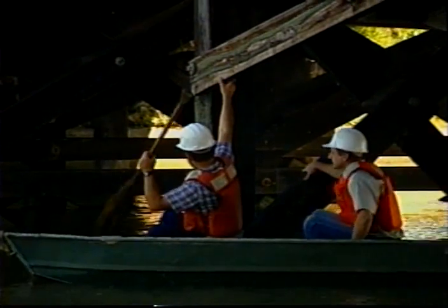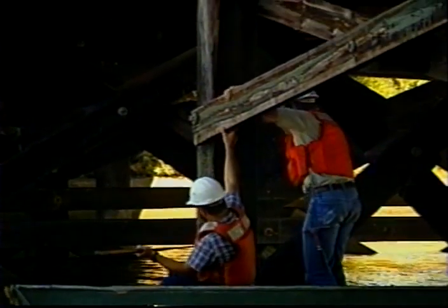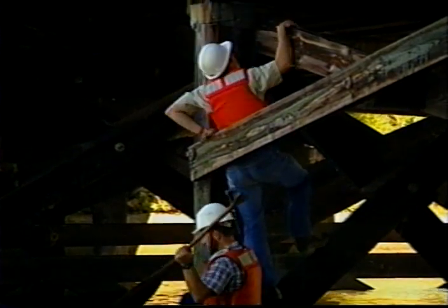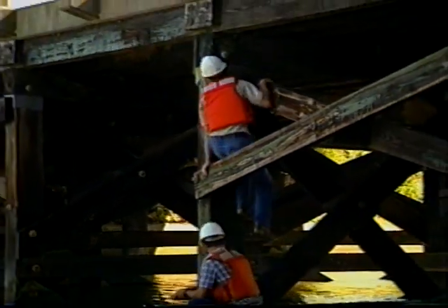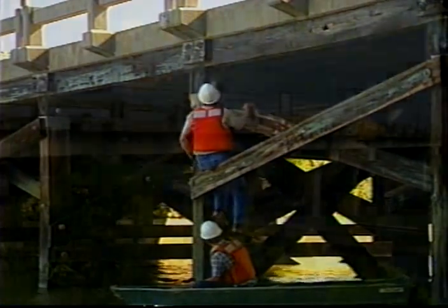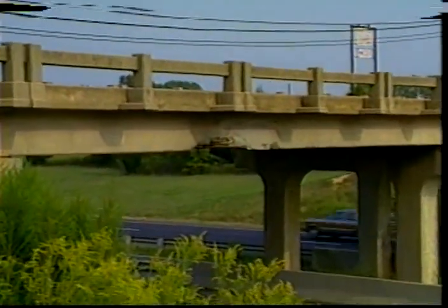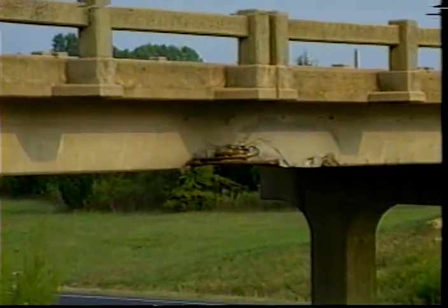Regulations generally require bridge inspections every 2 years. However, the National Bridge Inspection Standards accommodate variable inspection frequency depending on factors such as age, traffic characteristics, maintenance programs, and known deficiencies. Bridges in poor condition or having details subject to catastrophic failure should be monitored more frequently.